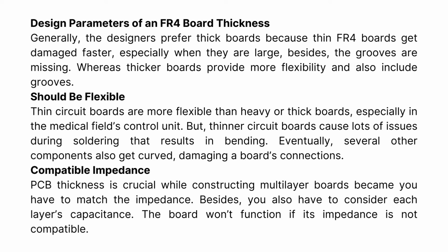Should be flexible. Thin circuit boards are more flexible than heavy or thick boards, especially in the medical field's control unit. But, thinner circuit boards cause lots of issues during soldering that results in bending. Eventually, several other components also get curved, damaging a board's connections.